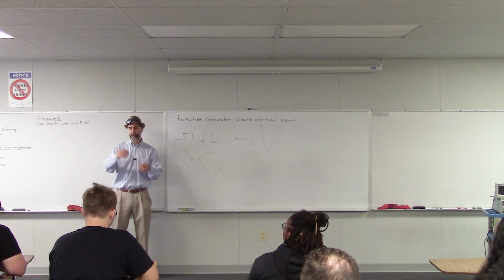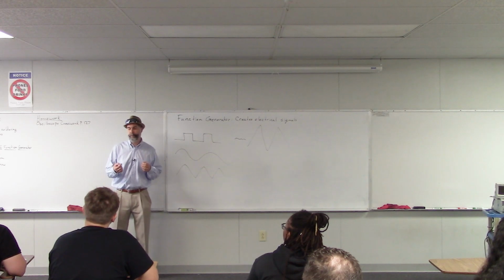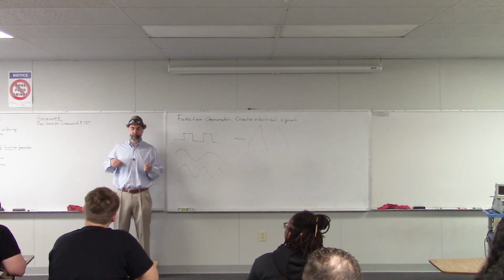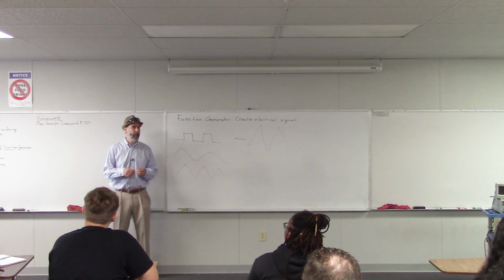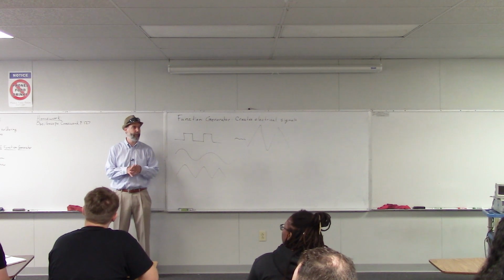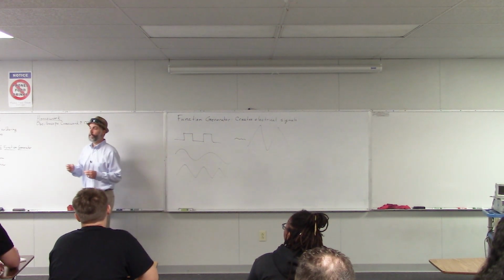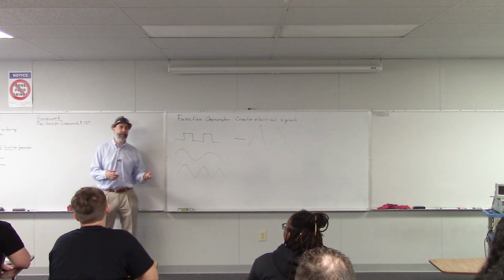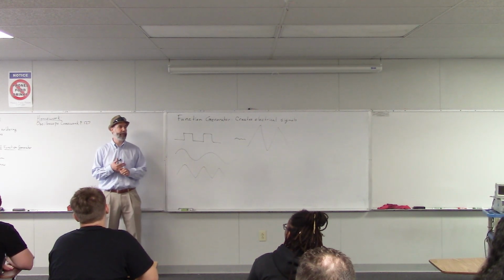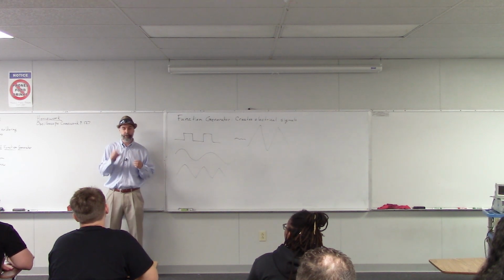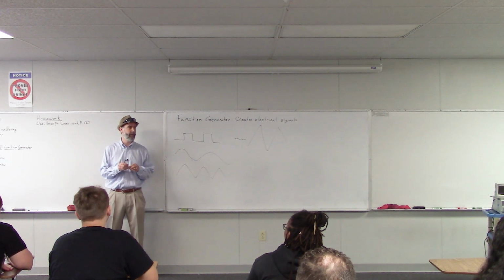And if you're just looking at the output, you'll have no way of telling whether those differences are coming from the way that you strummed your guitar or from a problem or a difference in the actual board of your pedal. So what you want when you're testing this pedal is you want the input to be super consistent, exactly the same every time. That way, when you look at the output, if you see any differences in the output, you know that they're coming from the circuit board itself.